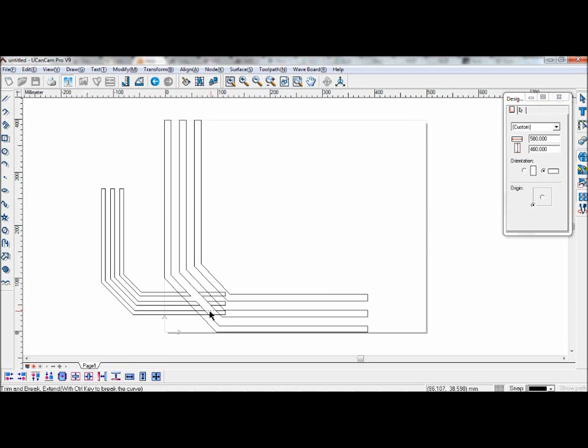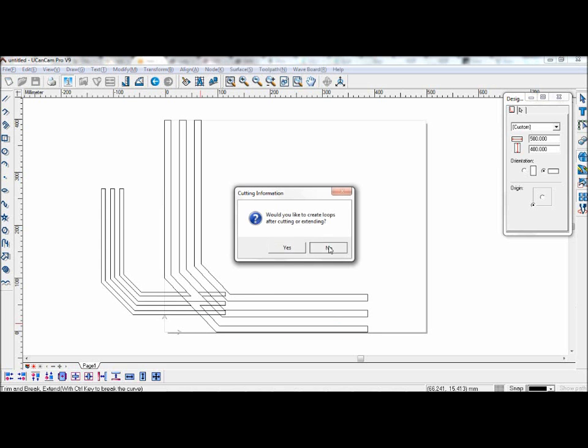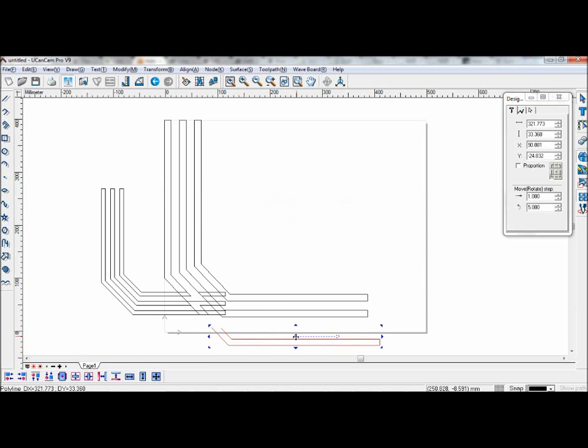To connect the lines again, hover your mouse over where the line should be. When you see the mouse is like this, with the dotted lines, left click, and they will connect. To separate the lines, or break them, hold Control when hovering your mouse over them. And when you see it has become the hammer with the blue dotted lines, left click, and you can see that it has become disconnected from the original. If you wish to stop editing, you can right click or press escape.